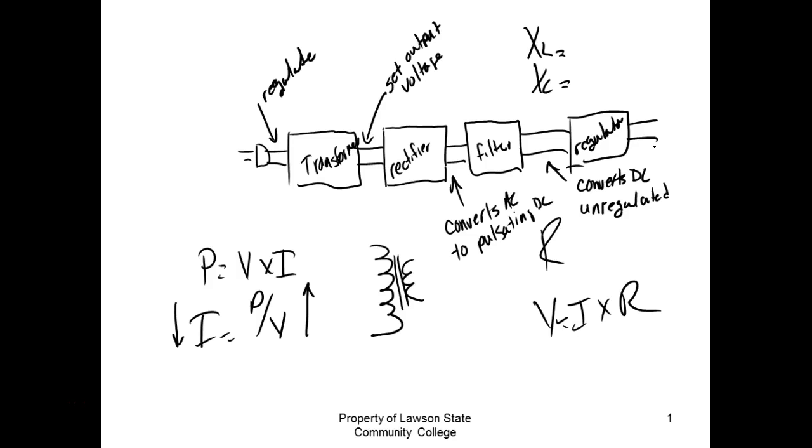Well, you put different loads on there, but it's going to have set limits, right? You understand? If you design it around 5 amps and you try to get it to run 30 amps, it's going to go out of regulation. Or if you design it with a minimum voltage of 90 volts, and for some reason your power drops down to 80, then it's going to go out of regulation. And a good example would be your cruise control on your car.